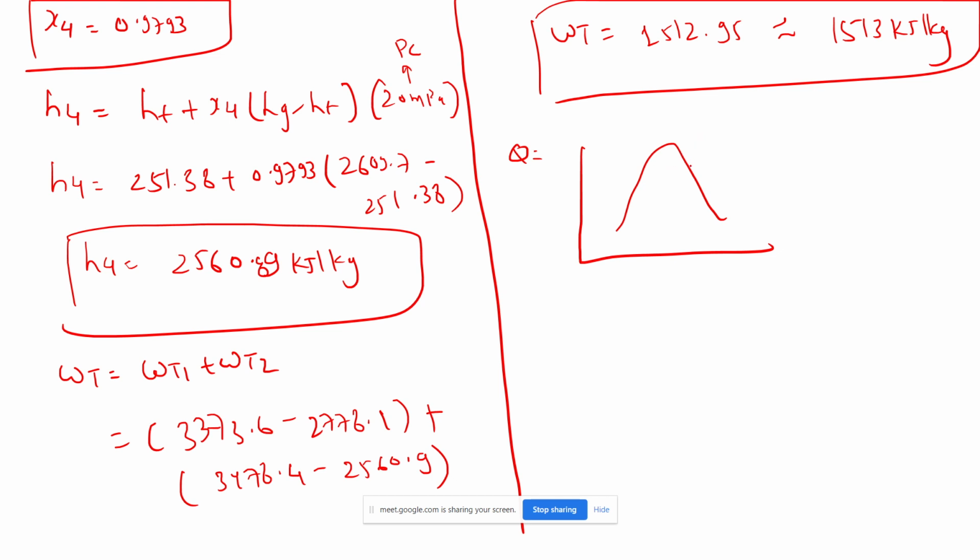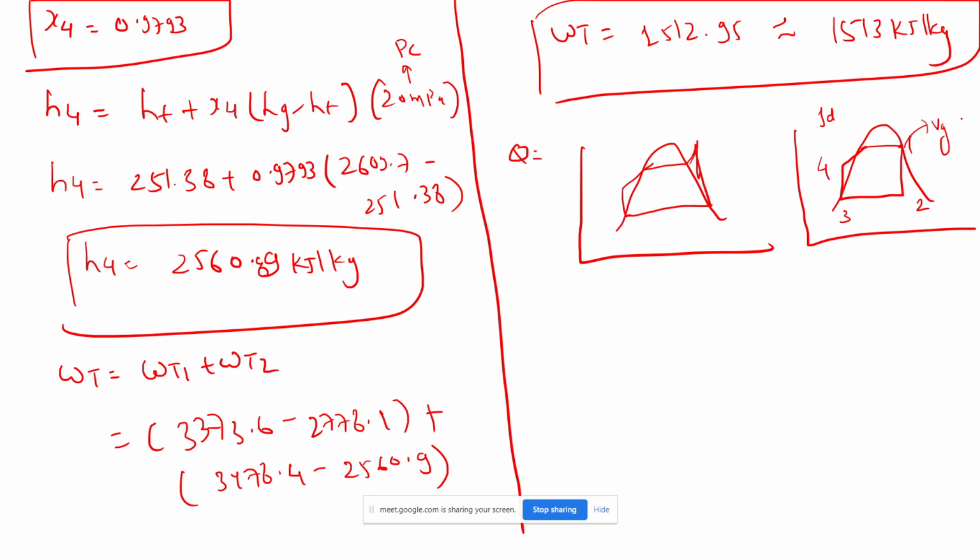Actually, when nothing is mentioned, then yes. But in this question they have mentioned that a superheated steam enters the turbine. So it is an ideal cycle, but the entry condition they have actually mentioned, so it is a superheated vapor. If they had not mentioned that, and only mentioned ideal Rankine cycle, then you have to take it as entering as saturated vapor, Vg. If nothing is mentioned, just consider that. If they have mentioned it, then you have to calculate according to that.